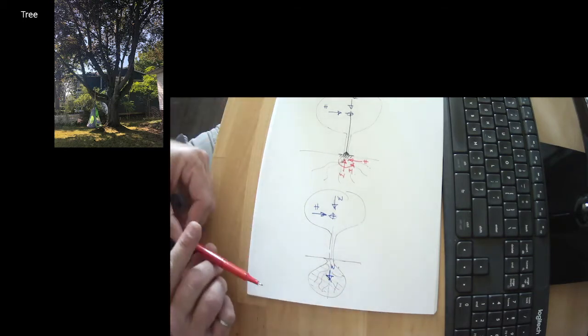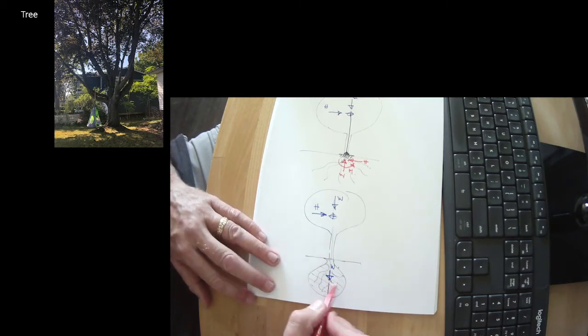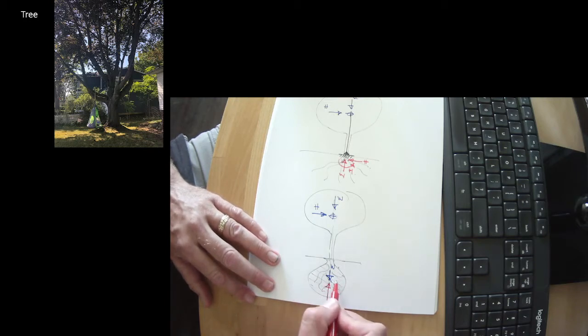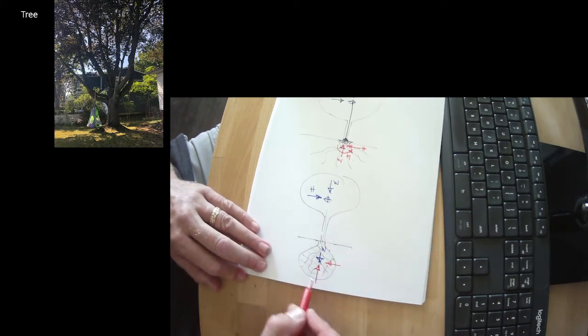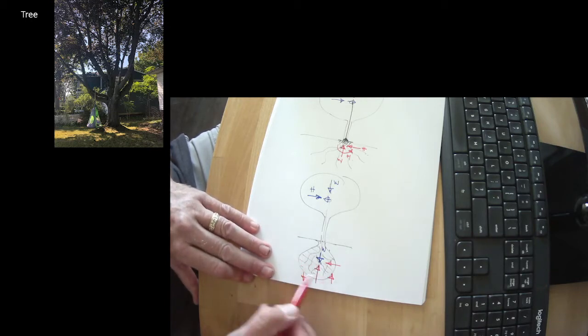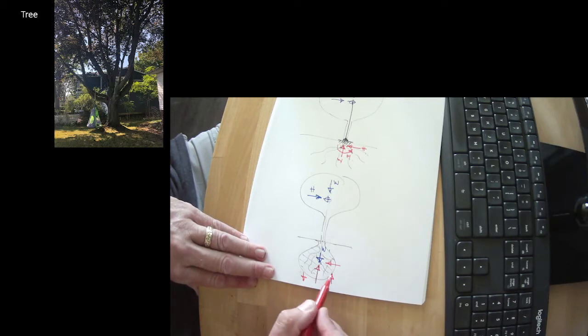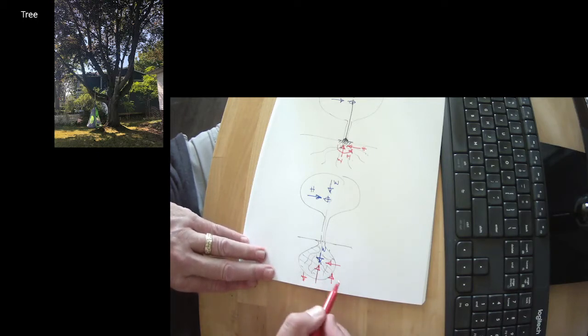And under lateral load, we wind up with a horizontal reaction here, and because this is large, we can actually develop a couple across the width of the root ball. So I'm representing it as a couple because it's interesting to think about it this way, but this is effectively what's happening.